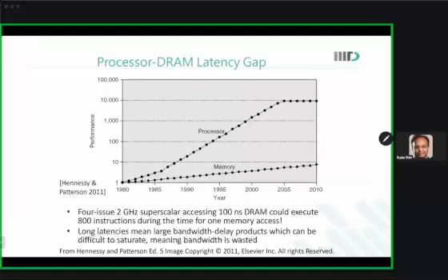It can only take one instruction and then execute it. If you have a high performance superscalar where multiple instructions can be taken, it can actually take 4 instructions and run at 2 gigahertz speed. So by the time it can access a DRAM, it could execute 800 instructions. So you see the mismatch of performance.